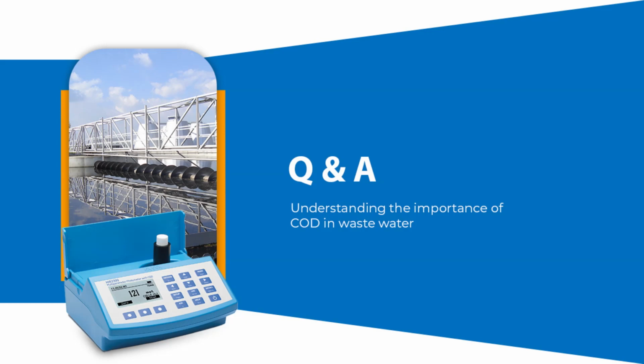And does TSS affect the COD value? After digestion, you have to take the reagent vials, and some particles are there. You have to let them settle down. If you disturb those vials, it will interfere with the reading of the COD values.